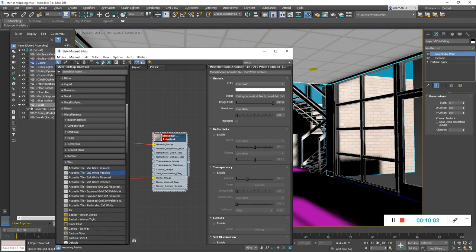Now, step number 10, it says you can reposition the ceiling texture through the offset fields in the Map Scalar modifier. In the command panel, in the parameters rollout, change the U and V offset spinner arrows to observe the change in the viewport. So if I just change that to 1 foot, it just shifts it by a foot. If I change this by 6 inches, it shifts it by 6 inches one direction or the other. I'm going to bring those back to 0 as they were.